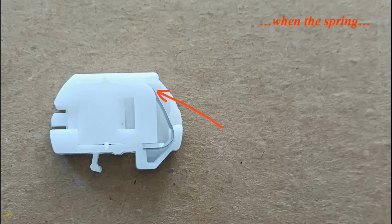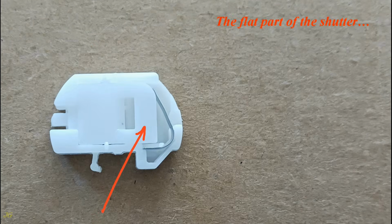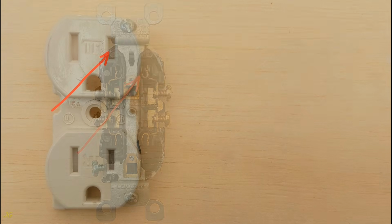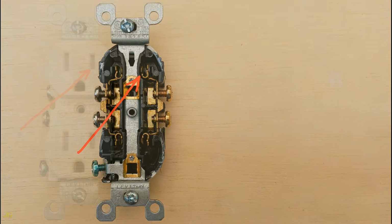When the spring presses the shutter to the side, the flat part of the shutter that covers the hot slot in the front base of the receptacle prevents contact with the hot female contact inside the receptacle.